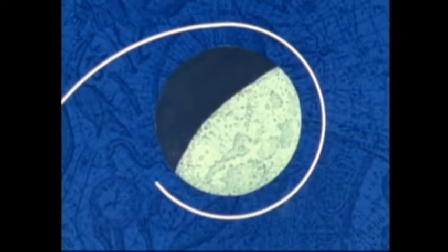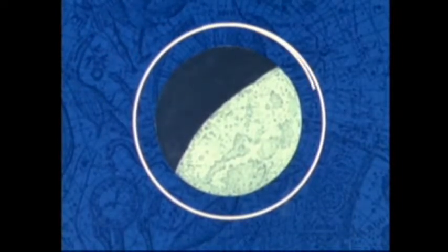Before presenting the actual entry of the Apollo Command Module into the atmosphere of Earth after its lunar expedition, we will review quickly the overall mission to this point. The Apollo space vehicle and its crew were placed in an Earth parking orbit, then injected on a trans-lunar trajectory. A burn of the service module propulsion system provided braking and a plane change that placed the spacecraft into the proper orbit for the lunar landing, the landing to be performed in the lunar module.